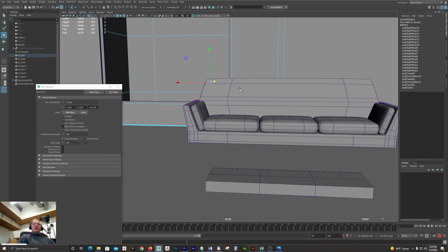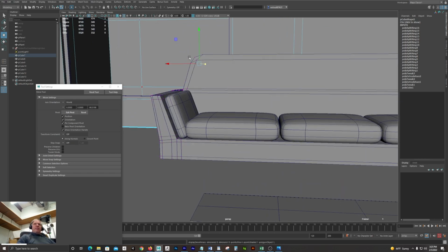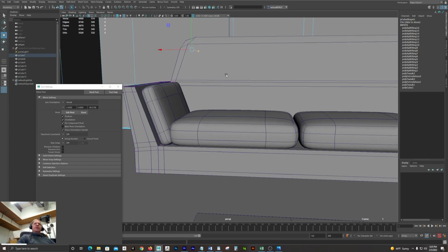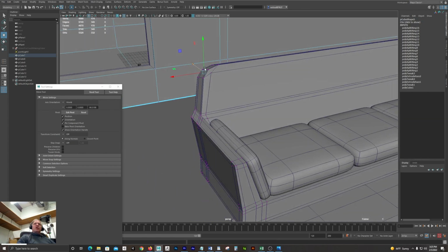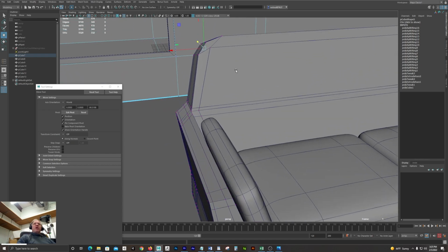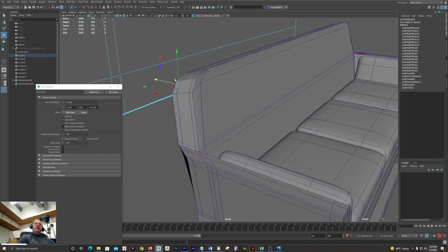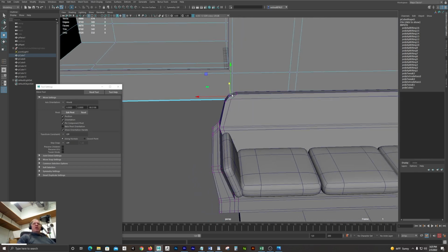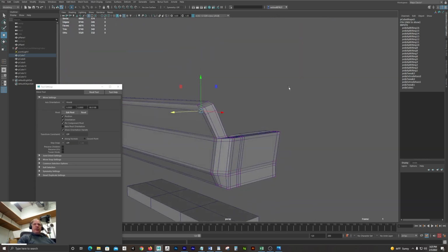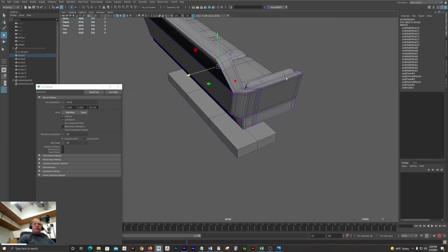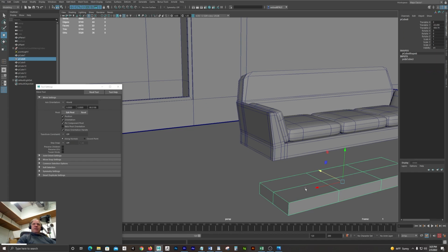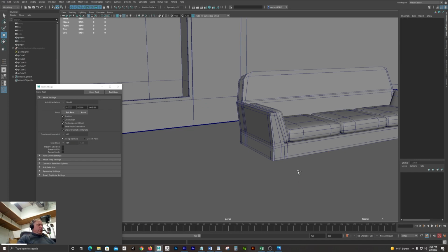And now I've got those nice smoother corners up here. And again, I did that by separating out the edge loops, the supporting edge loops that control how sharp that edge will be. And then to make sure it's in the rough as well, so it's going to take light better when I light and texture it, I drop that edge down physically as well. So not just a smoothing algorithm, it's me too. Okay, object mode, select this, I don't need it anymore, save.